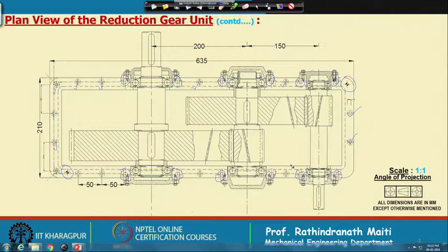And another issue I would like to mention here, that when we are putting these two covers and we are tightening fully, still there is a possibility of leakage through that. So, to prevent that, sometimes a very thin material like a transparent sheet is put there, which practically has no dimension, you can say, after the bolts are tightened.